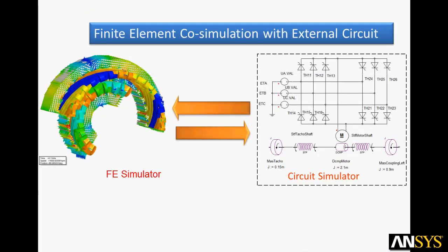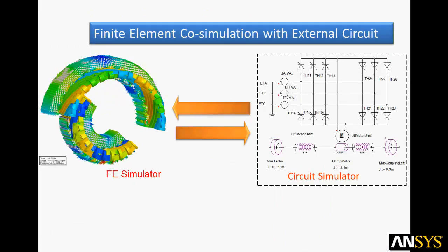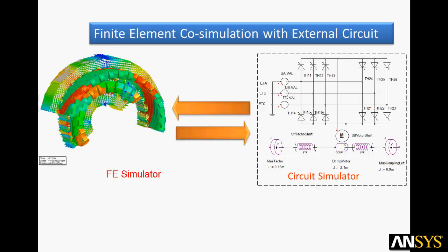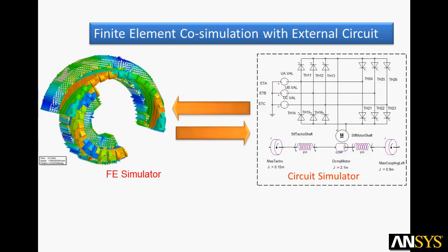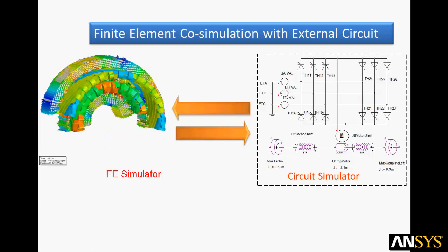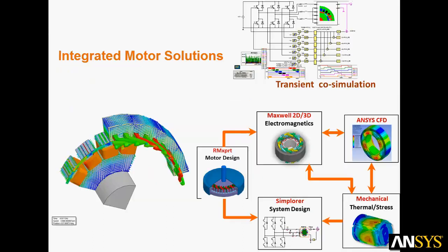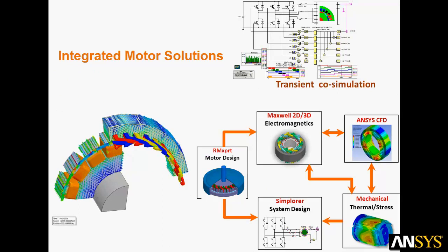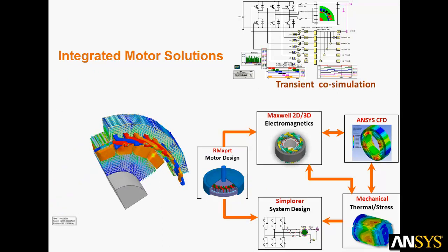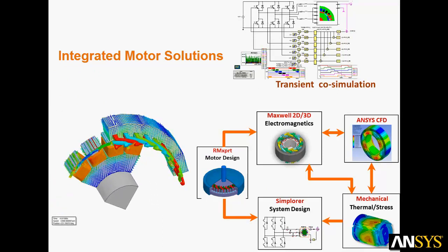Electric machines require appropriate electric drive circuits. Maxwell finite element analysis co-simulates with the Simplorer circuit simulator to evaluate how nonlinear behavior of the motor affects the drive circuit and vice versa. ANSYS tools allow you to simulate complete integrated motor behavior by linking physics and systems solutions.